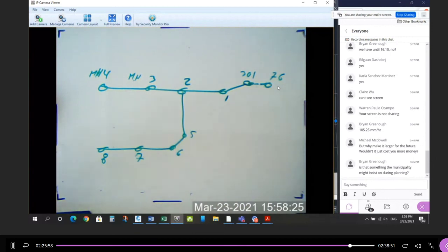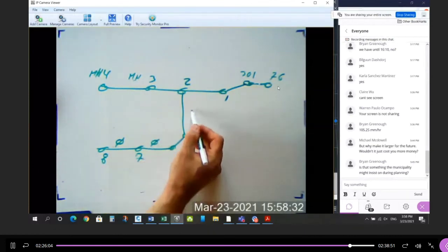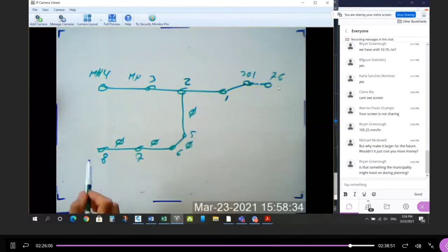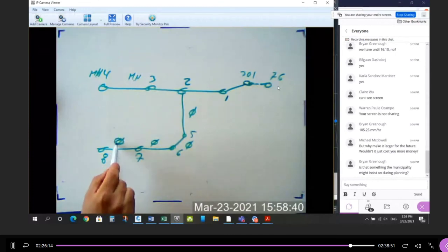Always design from the top down, right? So figure out this size before you figure out this size, before you figure out this size. Always design the hydraulic pipe size from the top, work your way down. Why? Because when you change the diameter of the pipe, or you change the slope of the pipe, it's going to change the time in the pipe.